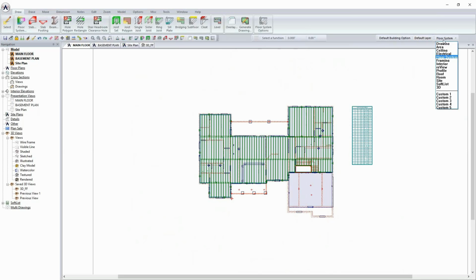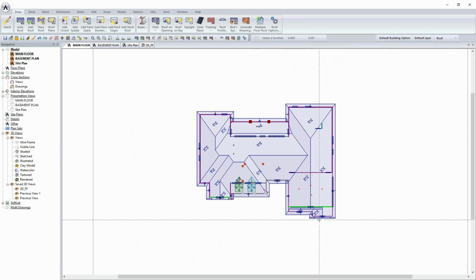Once you have done that, you would then go in through the roof mode and be able to place the roof. All of that allows the model to work. If we don't get the wall heights correct, then we don't get the opportunity to put a correct roof on, and sometimes in that case the roof is going to fail, and then you've eliminated at least portions of the plan, if not the entire model, from being able to be viewed in 3D.